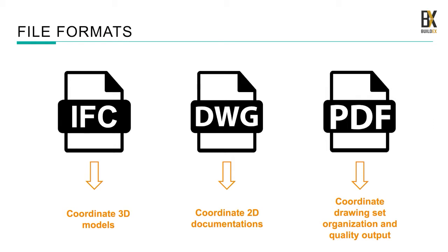You may ask, what are the formats used in the BIM process? This presentation focuses on the IFC file format, but PDF and DWGs are still part of the file exchange process. In my experience, we always exchange all three file formats, and they get used in different ways. The 3D will provide the geometry needed to locate the building on the site, and it also provides the data for each building element included in the model.